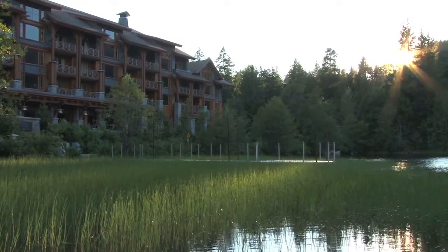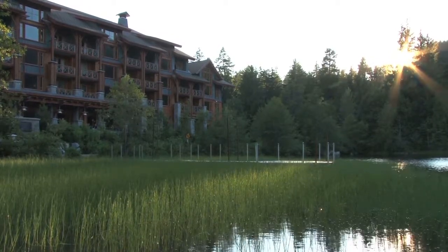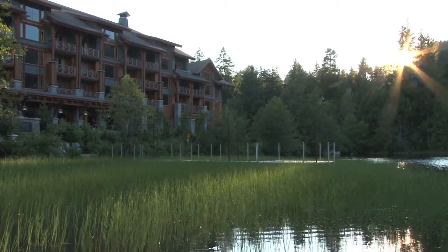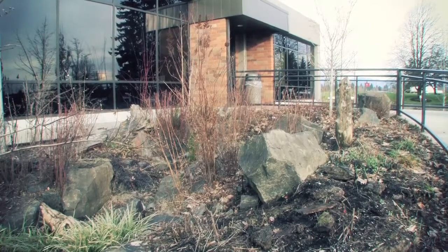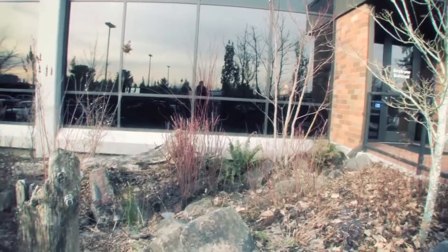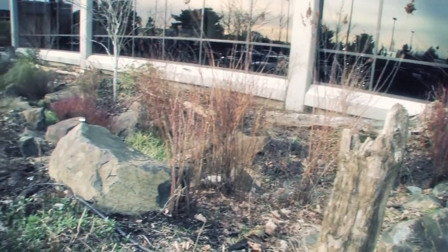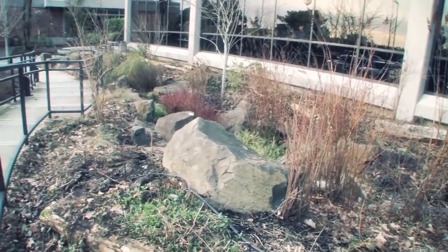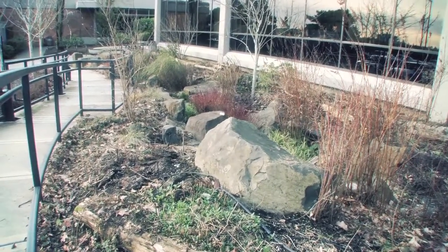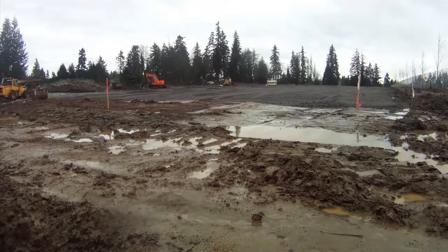Accordingly, highly centralized approaches such as large ponds or wetlands that manage all of the runoff from the master plan site do not meet the intent of this credit. Instead, design strategies to manage runoff as close as possible to the source and in such a way that the strategies best maintain or restore the watershed's hydrological and ecological functions. Examples include using swales instead of piping, promoting sheet flow to natural areas, and reducing the width of paved roadways.